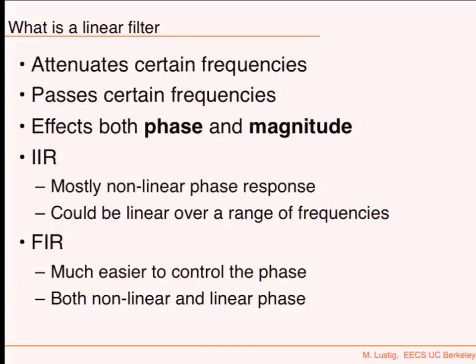At the same time, there is an advantage of using nonlinear phase. You can get sharper selection of frequencies for a lower order, for example, but you trade off this dispersion, or the distortion that you might get in whatever you're putting in. You'll get it more as we talk more about systems and what the phase response is, when we talk about linear phase and types of systems in the next chapter.